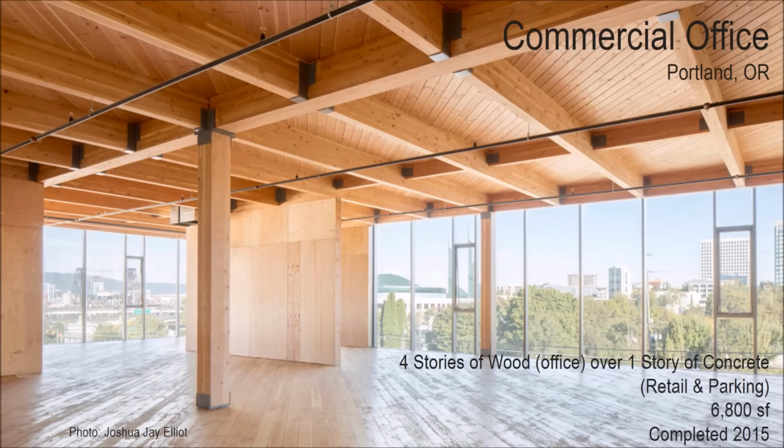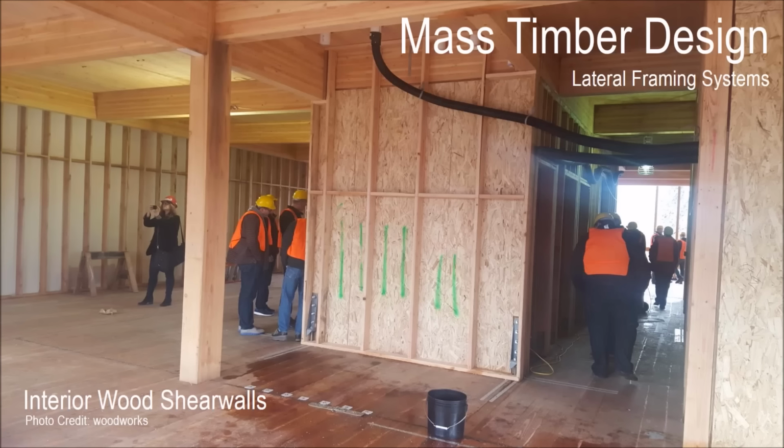The Albina Yard project that Michelle mentioned and I had pictures of earlier did the same thing. So this actually is a CLT floor, below and above this picture, and they used, again, wood structural panel shear walls as their vertical seismic force resisting system. This actually had most of the lateral resistance at the cores, and so these end up being double-sided core walls or shear walls.